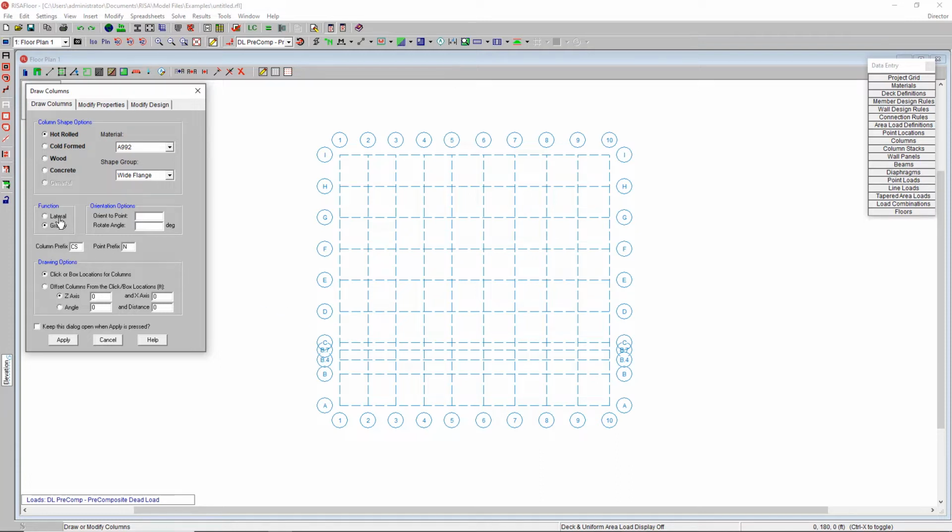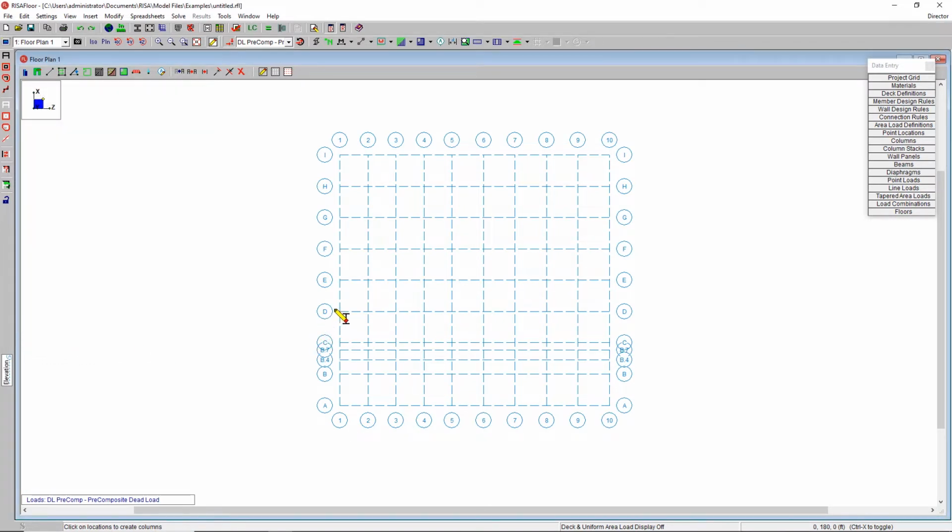So in this model here, I'm going to lay out that lateral system and just say here A992 wide flange lateral and let the program think about what it needs to go and where. So starting out, I just lay out some columns. I can just rubber band around the areas that I need those columns. So I will just go ahead and say rubber band this in this direction. As you see, I rubber band around the project grids. The column goes in place there.